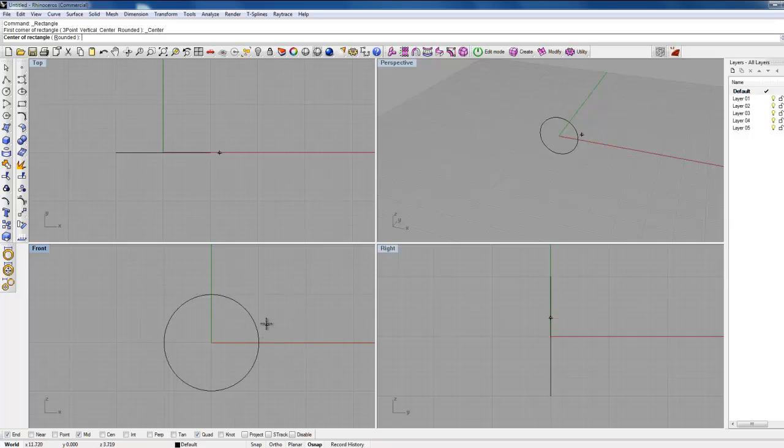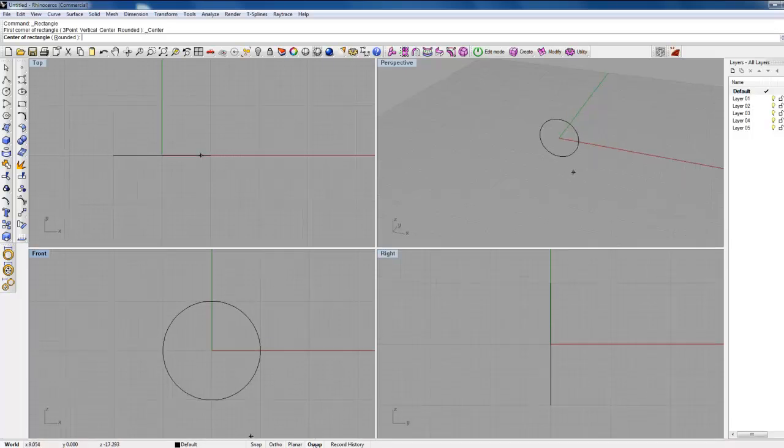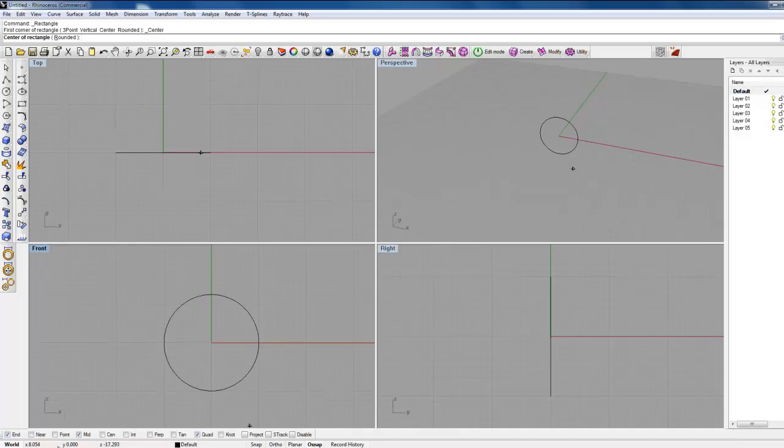So you need to make everything touching. There's a thing down here called O snaps. So if you end, mid, you can select whatever you want. I'll explain that in another video probably, but you want end and mid on, and maybe quad as well, doesn't matter.